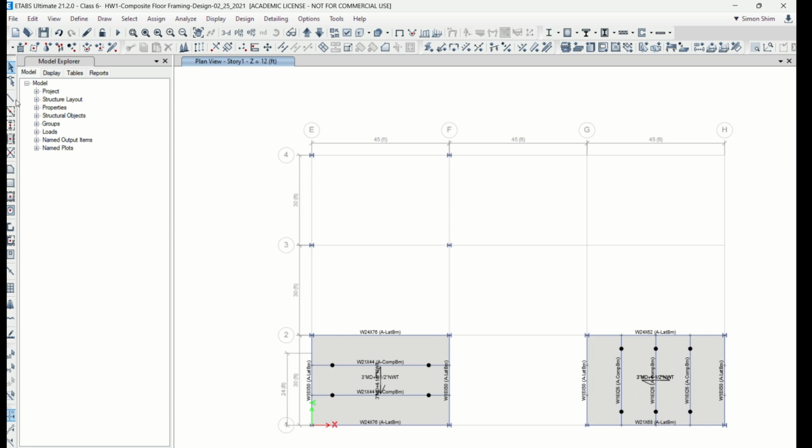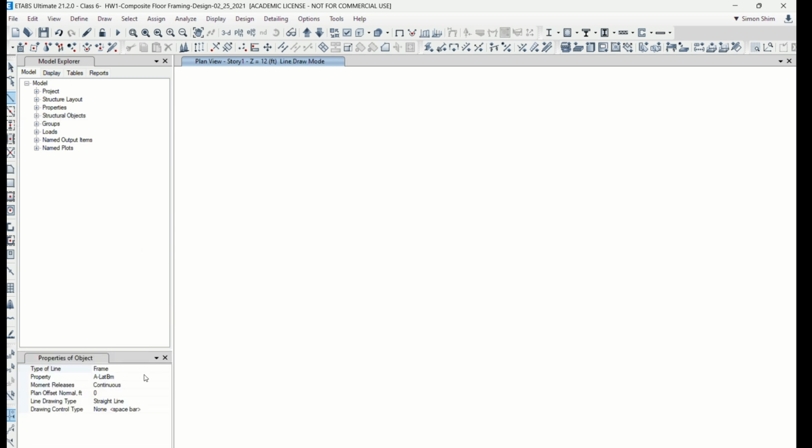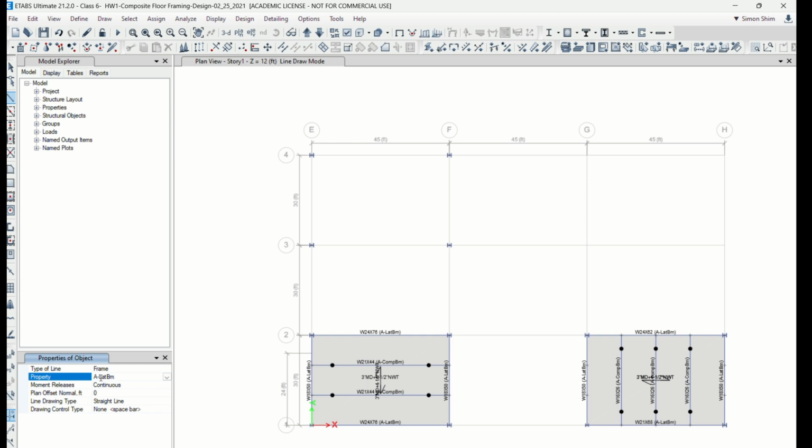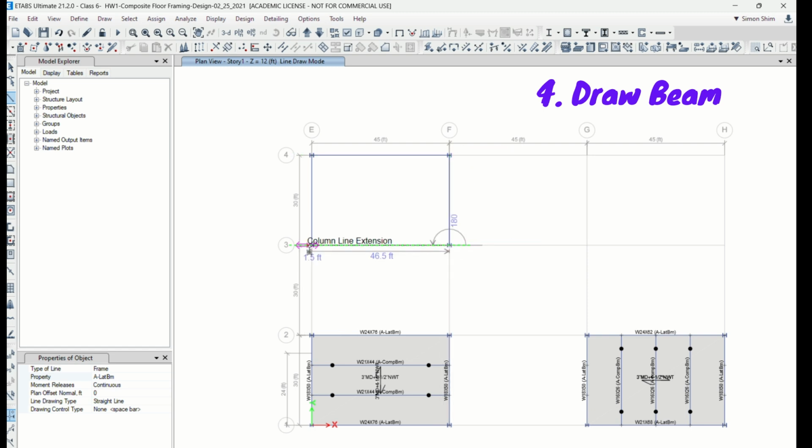So now, second, I'm going to click the beams. I'm going to draw the girder to tie the columns. This time, I have a default here, lateral column beam, lateral beam. It's part of the auto selection beam, but I assume this is a moment frame because this is a 3D structure, so I need to at least have some lateral stability. So I'm going to keep drawing the girder.